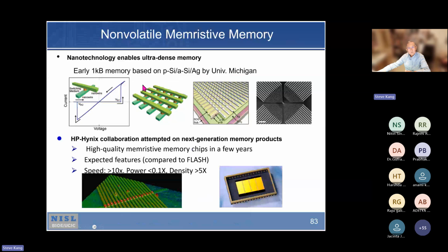And this is what's called the crossbar array. So you have an array of nanowires, top and bottom. In between, you have a sandwich structure. So each brown one is a memristor, actually. That cross section is a memristor. So in this case, it's 4 memristors, a 4x4 array in this particular case. And then again, you have a Lissajous figure like this. Right? So this one has 2 distinct states, high resistance state and low resistance state, right?